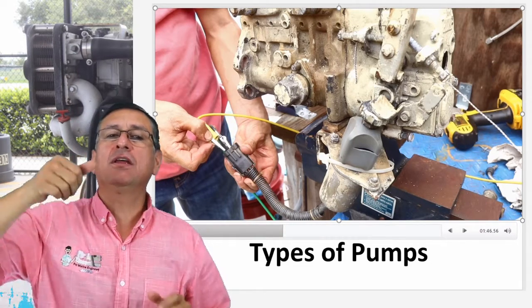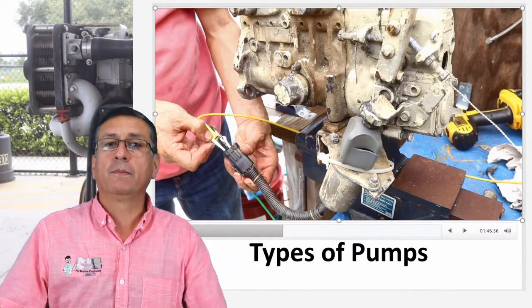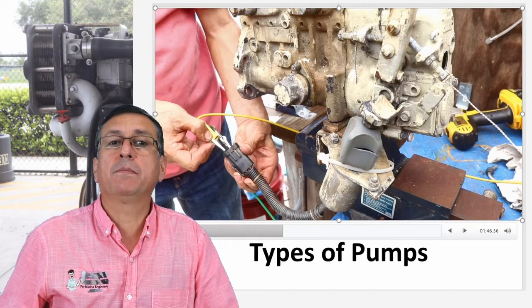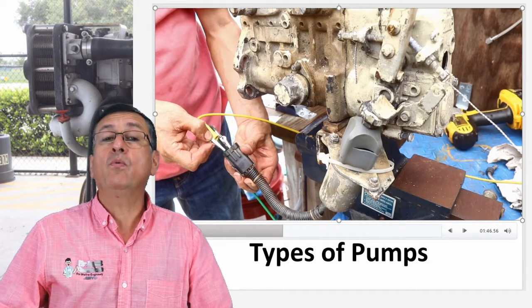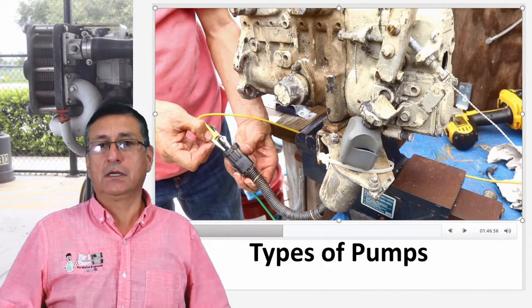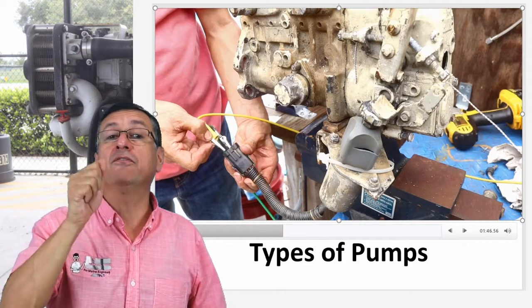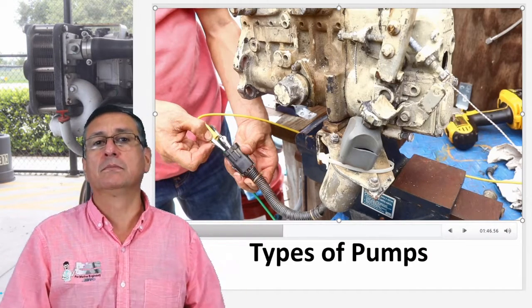Yeah, in a diesel engine, when you press the stop button, you activate that solenoid and the engine stops. You cut the fuel. There are two ways to stop a diesel engine. One way is when you cut the air, no more air, and the engine stops. Or when you cut the fuel and the engine stops.